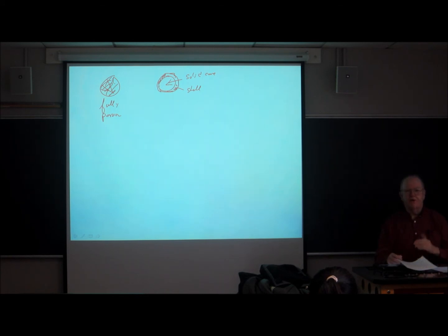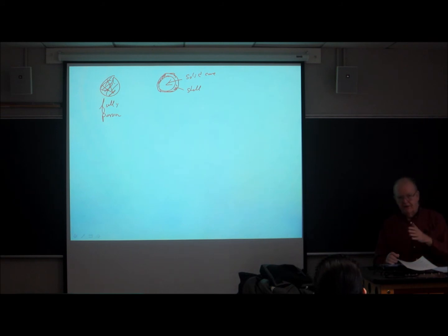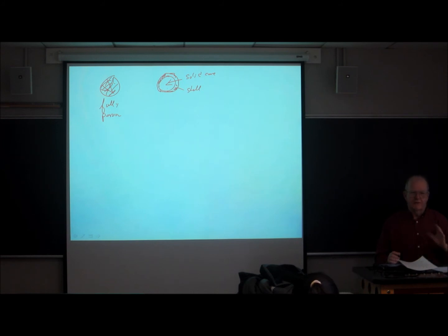These obviously don't have as much internal porosity as a fully porous particle. It depends on exactly who you buy it from. So I really can't tell you a good number to use for the porosity of this kind of particle. It's greater than 0. It obviously has to be less than fully porous. I think it depends on how thick the shell is and so on and so forth. So you have to look at the manufacturer's literature to come up with an answer for that problem. Okay.